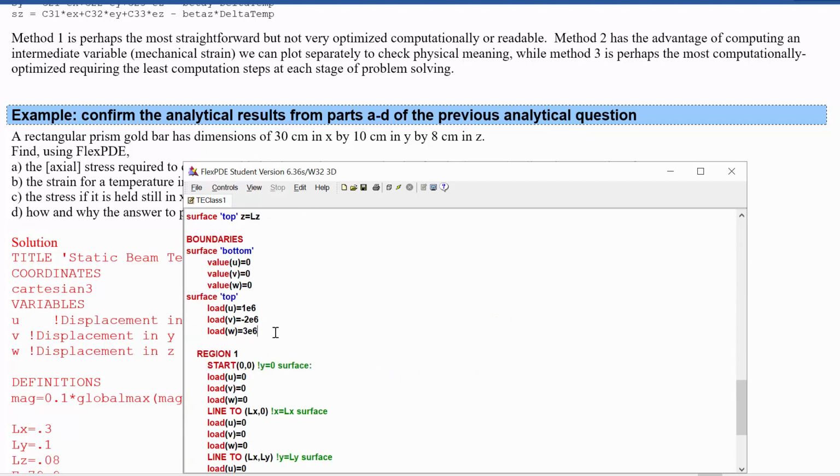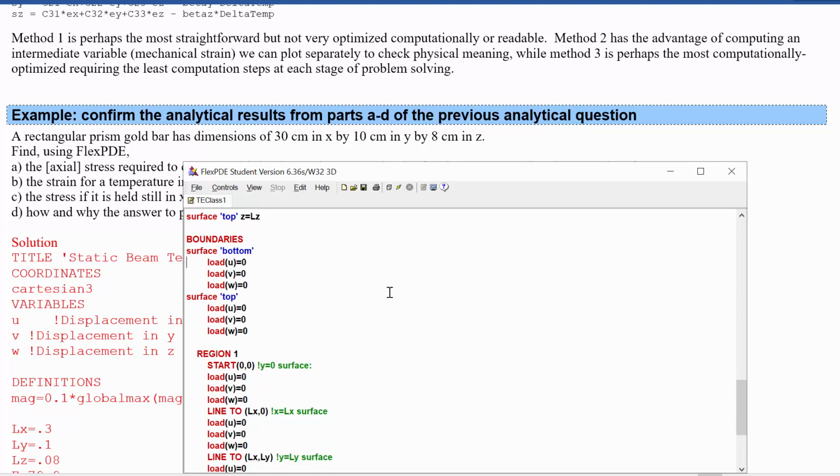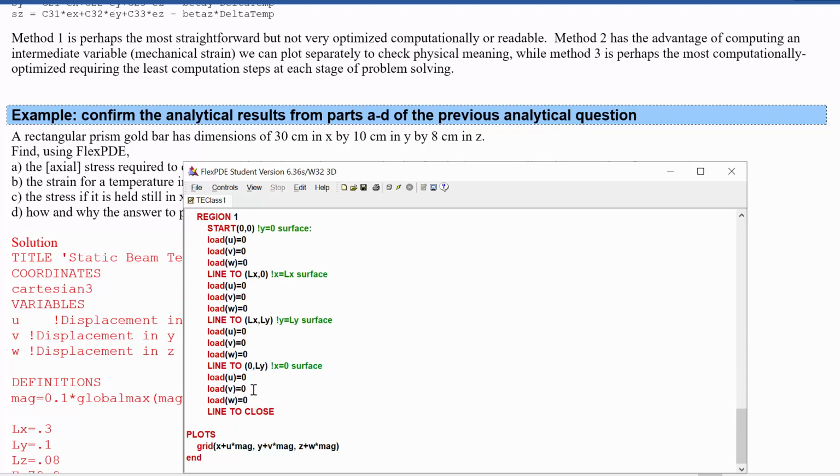Now it should be working, except that the boundary conditions aren't quite right. So we're going to have it free on the Z surfaces. So we can replace these all with load equal to 0. I'll need this value equal to 0, 1 for the X equals 0 surface, though. At least in the X direction for now. We'll be changing this up a little bit later.